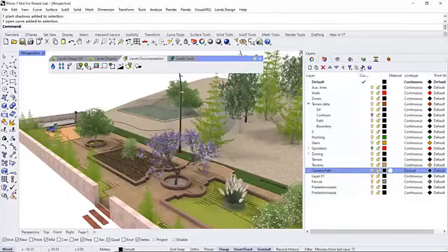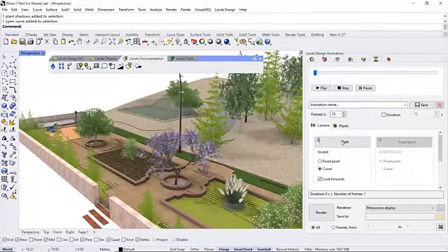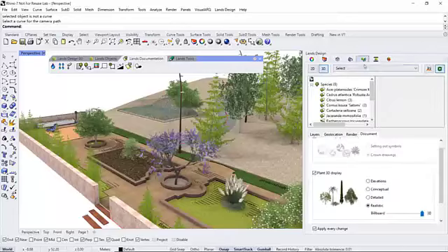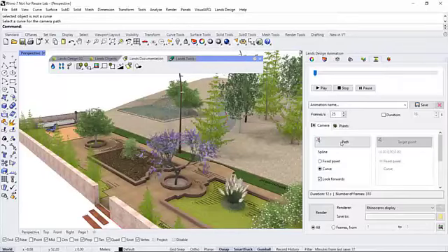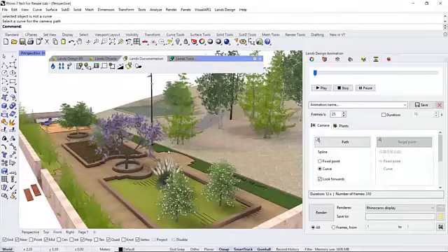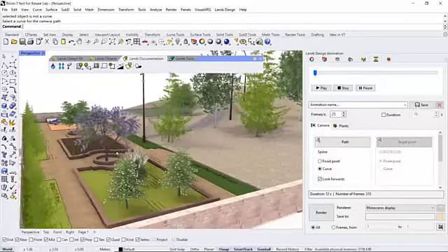It's this one. From here I need to click on this button to select the path curve. Now we can already hide it, so it's already linked with this path, and when we play the animation we are not going to see it.